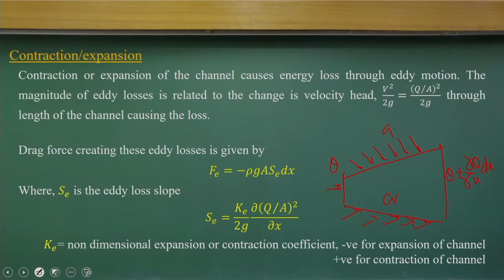That is the flow coming in this direction. This is my control volume, and the distance is dx. If q is the volumetric flow coming into the control volume, we can approximate the flow variability at this surface using the Taylor series. In the same way I can write rho beta q as the momentum flux, where beta is the momentum correction factor considering the velocity distribution.